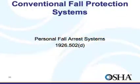Lastly, we'll take a look at what may be the most widely used form of fall protection in residential construction: personal fall arrest systems. A personal fall arrest system must be designed so an employee cannot free fall more than 6 feet or contact any lower levels, bring an employee to a complete stop in 3.5 feet, and have sufficient strength to withstand twice the potential impact energy of an employee free falling a distance of 6 feet or less.